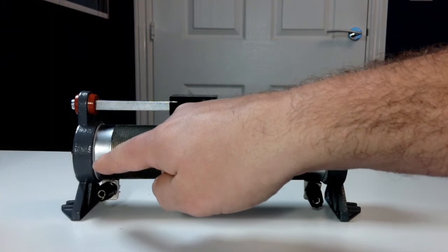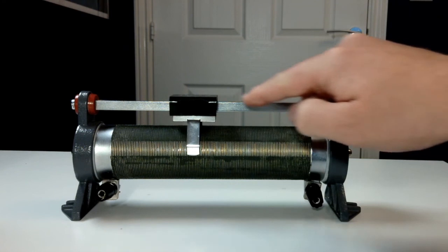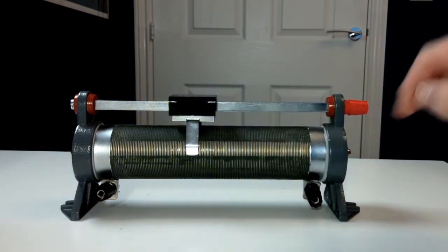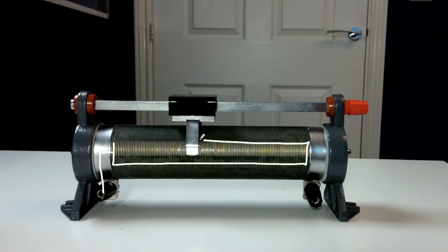Here is a rheostat. Along the bottom, we've got this long fixed resistor. Connecting across the top, there's no resistance in that wire, but then we can connect anywhere along that fixed resistor. So what does it look like if we were drawing the circuit diagram? Well, it's a fixed resistor along the bottom, and then we've got an arrow coming in wherever we like. Rheostats are really useful in experiments because not only can you easily adjust their resistance, but also, even when they get quite hot, they have a very constant resistance.